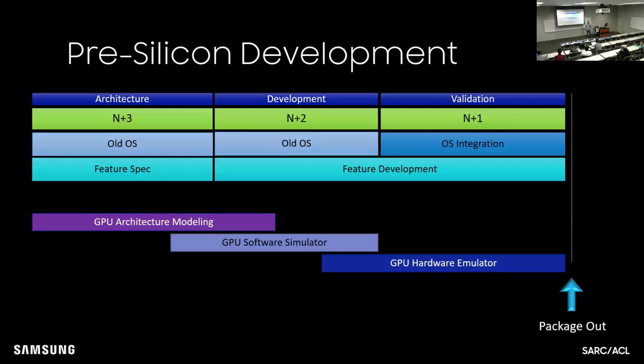How do you do development when you don't have a device in front of you? A lot of that has to do with using architecture models. These are like C models where they functionally create what the chip does in small portions using a batch server farm, where each part of the GPU runs on a different thread, and then it's running, and it's literally doing everything exactly how the hardware would do it, and we call that a C functional model.